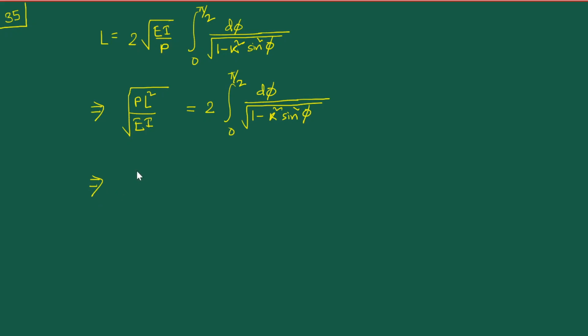And then we write it in this way, pi square EI by L square. The motivation of suddenly bringing about this term here in the denominator, through the introduction of this pi square, is that we know that this particular thing is nothing but the Euler buckling load.